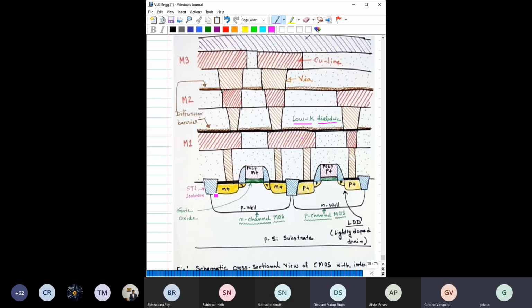Suppose here I have used STI, shallow-trench isolation, to isolate devices. I may ask you to draw the steps using LOCOS. Okay, what would be the steps? Or maybe vice versa. Here there is only one channel, using both the P well and N well. I may ask you to use only P well, or use only N well. That way the process flow would be somewhat different. So you should have the understanding and be able to modify those process steps accordingly. That is the expectation.